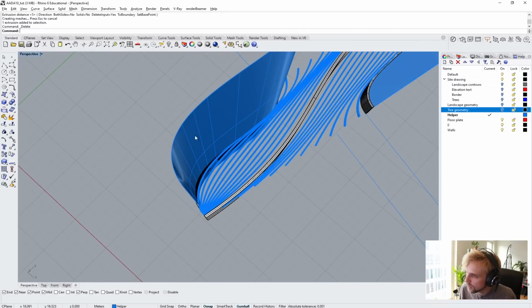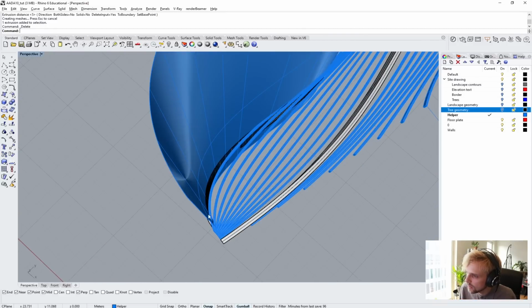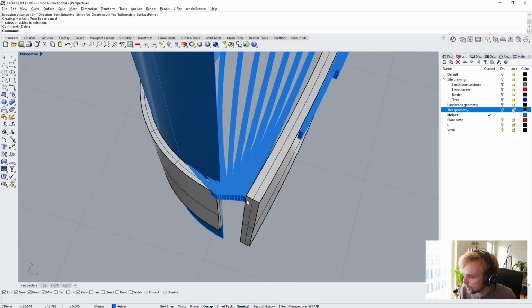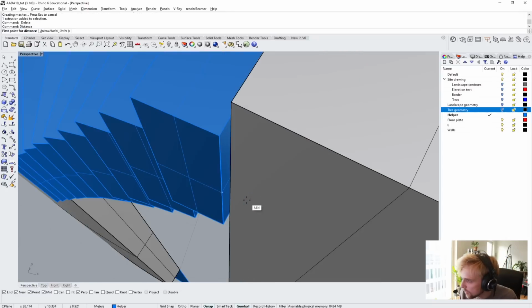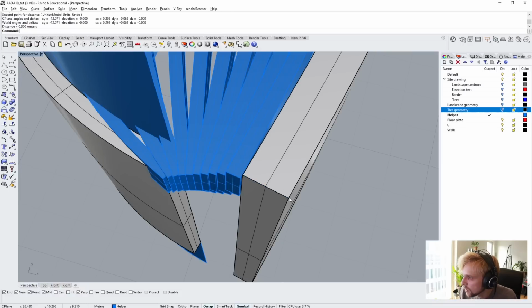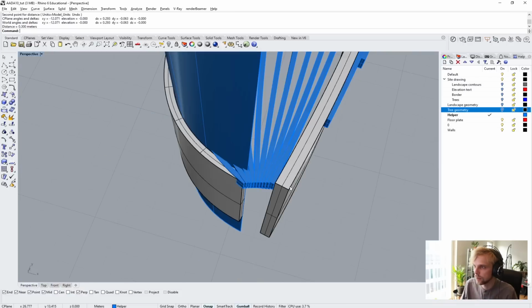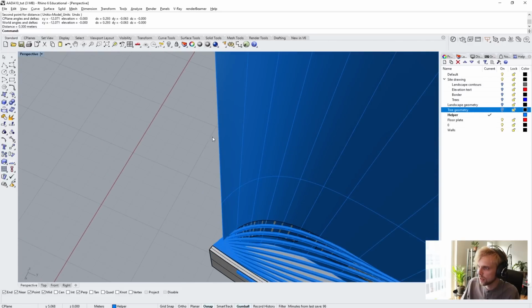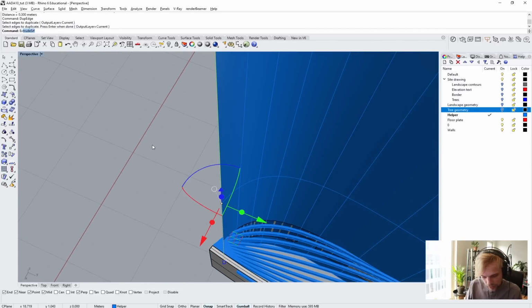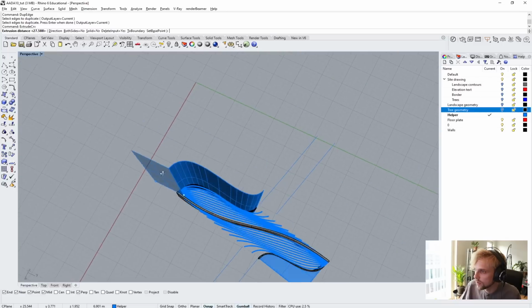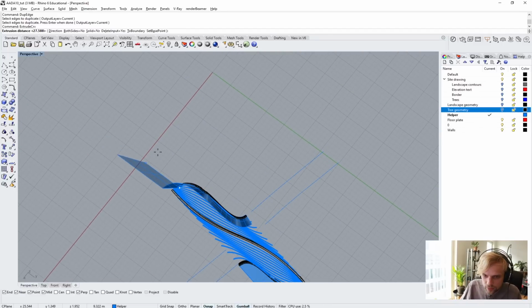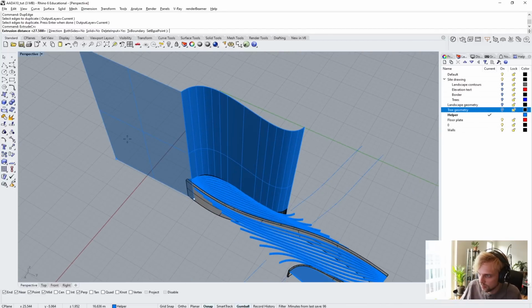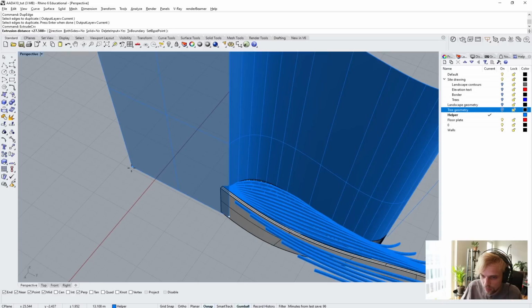And fortunately, this curvature here ends at a 90 degrees angle, which means we can use this direction from here to here, right? We can use that direction to take this edge, duplicate edge here, and use extrude curve on it. So now you can see when I use extrude curve, the direction is obnoxious. It's definitely not what I need.